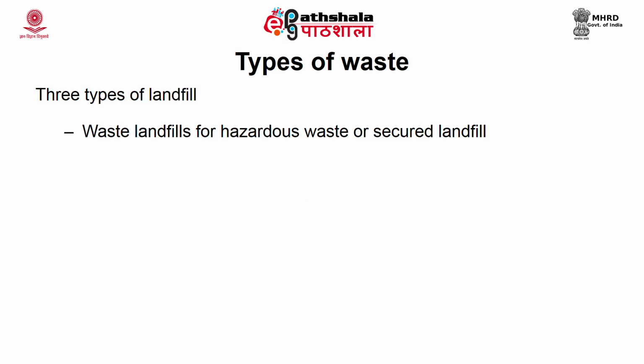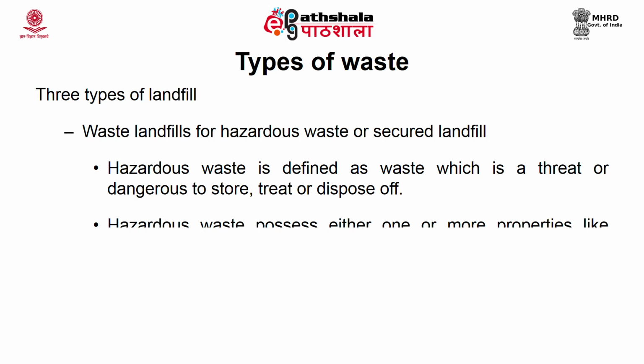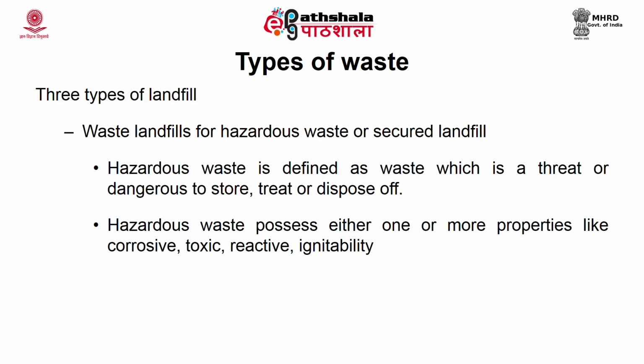Now, first we look into the hazardous waste or secured landfill. Now, you all know what is hazardous waste. Hazardous waste is defined as any waste which is very dangerous, which is dangerous for storing, it is difficult or dangerous to be treated, or it is dangerous to be disposed of. A material is called hazardous if it possesses one or more properties which are listed here, that is corrosivity, toxicity, reactivity and ignitability. In short, you call it CRIT, C-R-I-T.